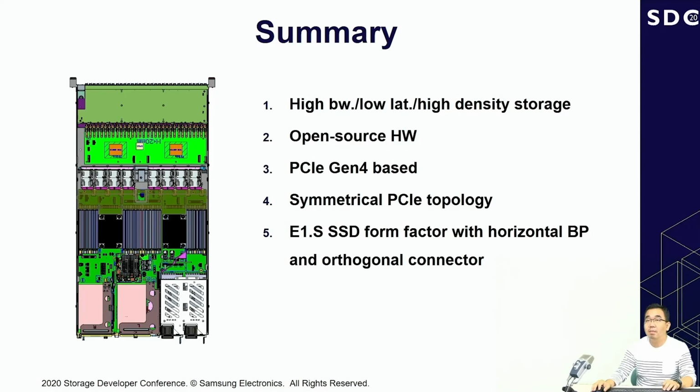In summary, the Poseidon system is a high bandwidth, low latency, and high density network storage system, and is open source hardware based. It's also PCIe Gen4 based, and we designed the system PCIe topology symmetrically. We also adopted the E1.x form factor with horizontal backplane and orthogonal connector to increase the system power efficiency further.